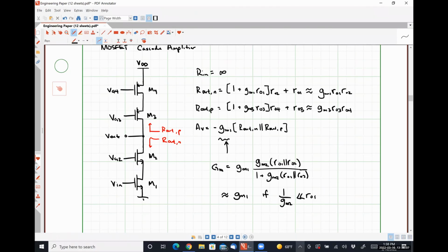It's only true if we design the transistors to have the same area, okay? So we can play around with things and actually change transconductances, change output resistances, all that kind of good stuff by playing with the aspect ratios and the physical size of our transistors to get whatever specific point we want. So there's a lot more flexibility for the designer in a MOSFET based configuration than there is in a BJT based configuration. That's why I'm not going through here and lumping things together and calling this gm times r naught squared. It's not guaranteed as much as it is in an integrated BJT.